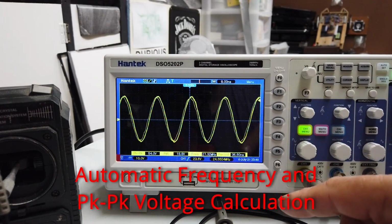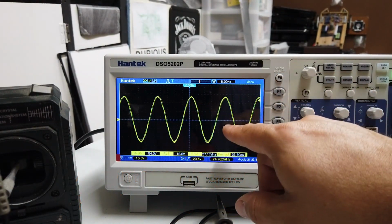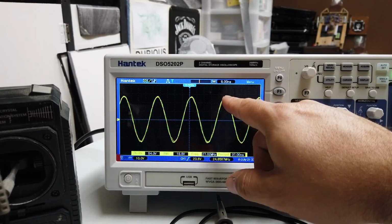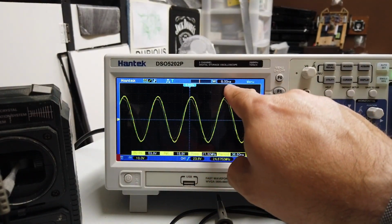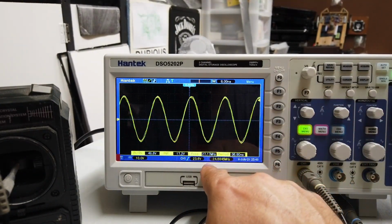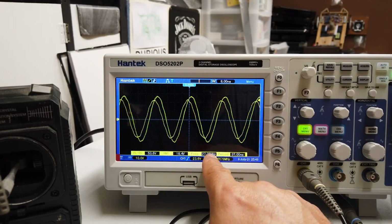So normally what you would do with an oscilloscope is count how many time-based graticules there are. In this case it's 1, 2, 3, 4, about 5 time-based graticules, and then you would use the time-base value, which is 8 nanoseconds, and do some calculations and calculate the frequency. But actually, in this case, the scope tends to do it all for you, which is really nice.